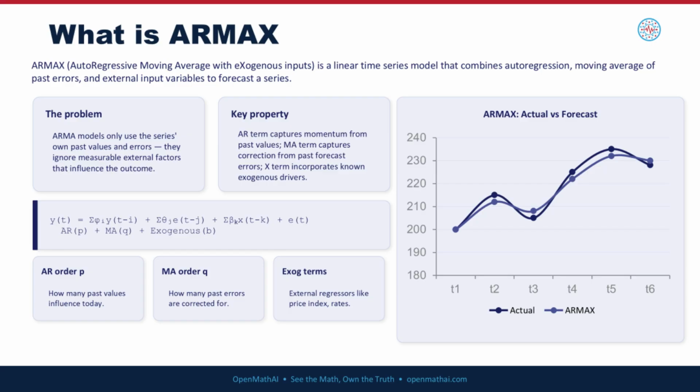output of a system. Unlike traditional regression models, which mainly use current input values, ARMAX considers previous outputs, external inputs, and previous prediction errors. The autoregressive part uses previous output values to represent the memory of the system. The exogenous input part uses external variables that influence the system, while the moving average part uses previous prediction errors